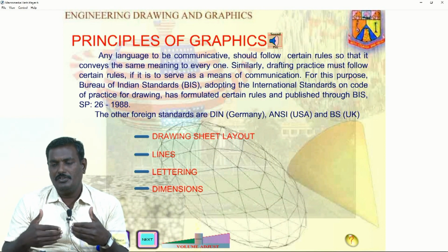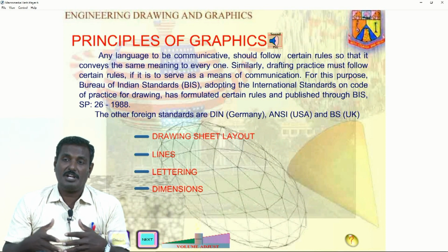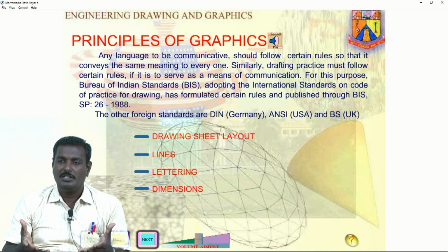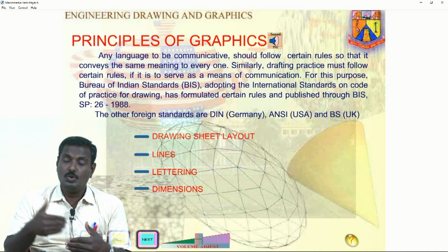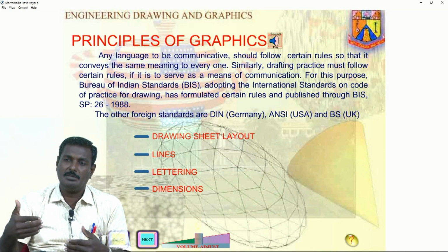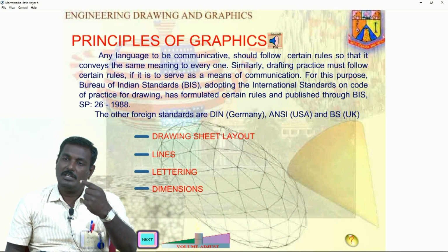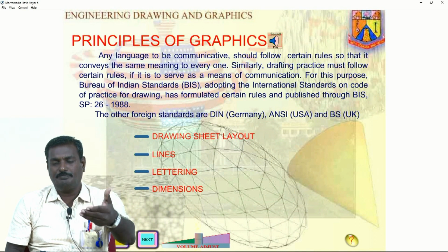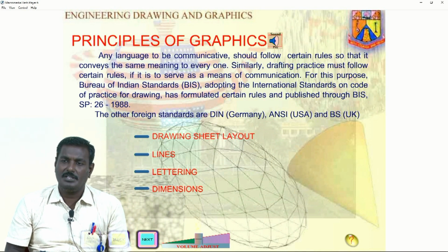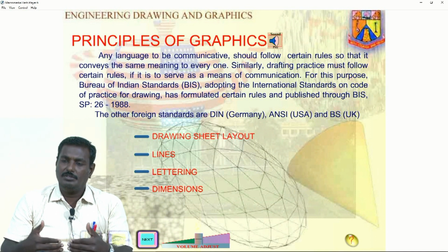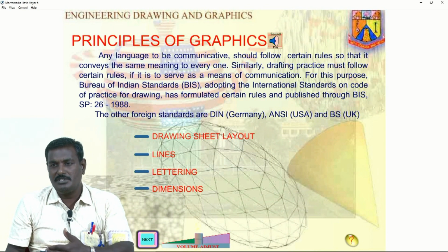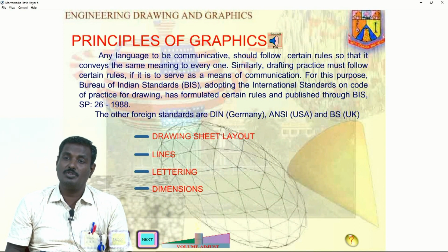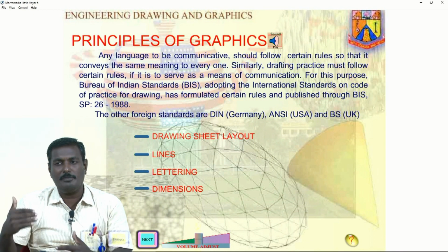Not only that, in any drafting, in one of the corners you must show the details. What details do we give? Who is the developer, who is the drafter, who did this drawing, with reference numbers. Also what type of drafting it is, whether it follows first angle or third angle projection, which we will learn in further sessions. Those details, with the date, should be entered in the right side from the bottom.